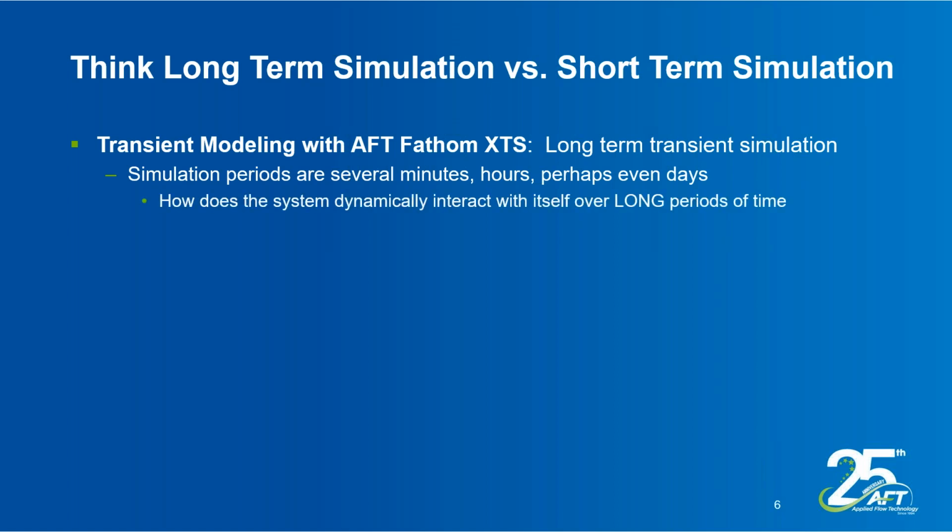Perhaps you have pumps that are simply changing from one particular pump speed to another pump speed, or maybe you have several different flow demands that are changing throughout the day. As your flow demand changes, you might want to see how your pump is going to change its operation on its pump curve. And you would look at longer periods of time. Those are the types of things that you would look at with AFT Fathom XTS.